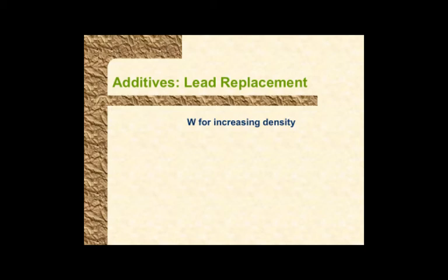The viscosity is too high. Viscosity is too high, it becomes more difficult to mix. Correct? So that means you might need a new mixer geometry. Right? Or it is a lot easier to get poorly mixed materials when you're dealing with our set of processes. And so agglomeration and dispersion become a big issue.